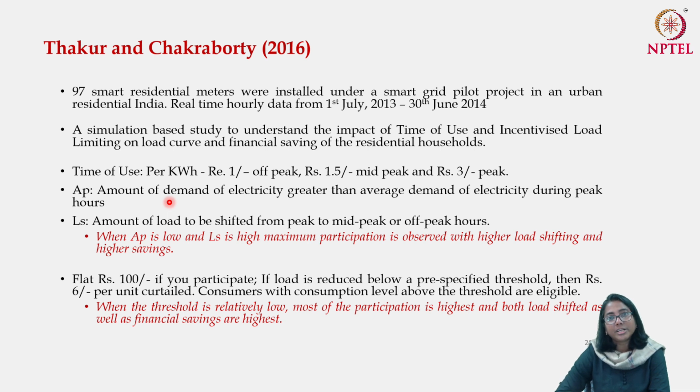Now, one interesting observation, if you go through this paper, is that you have to really intelligently choose AP and LS, because if you are not setting up your incentive in the right manner, and there happens to be a lot of load shifting, then instead of flattening the load curve, you may end up having a new peak during the off peak period. That is also possible. So this kind of simulation actually gives you an idea what should be the optimum tariff structure, what should be the optimum load that you want to transfer, what should be the optimum gain.